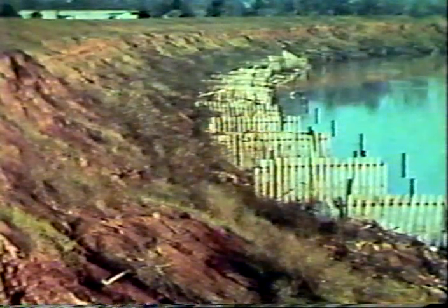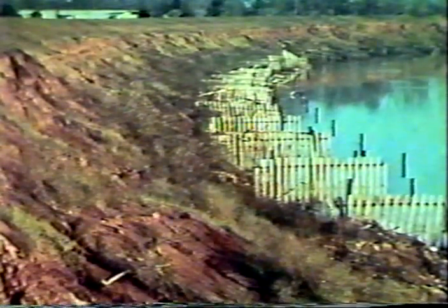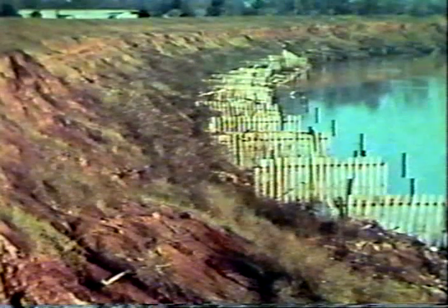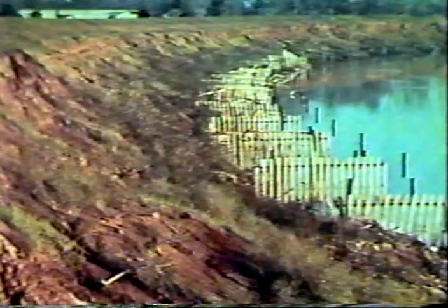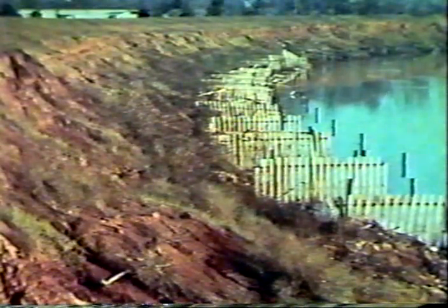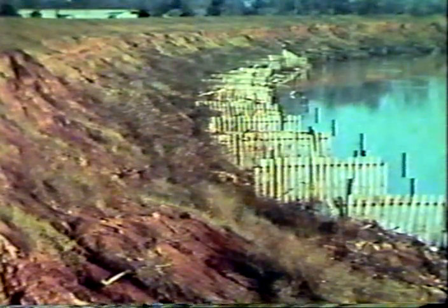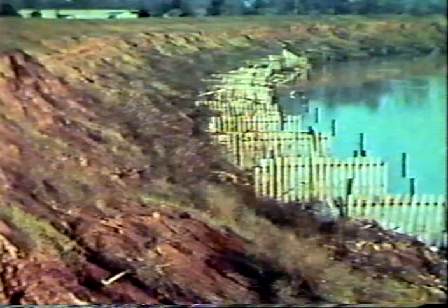These timber pile spurs on the Big Black River in Mississippi, installed in 1950, have successfully controlled the problem of lateral erosion at the outside of a bend. Patented permeable spur jetties, like these on the Brazos River in Texas, have performed well at some pipeline crossings. Permeable panels of timber and steel are loosely bolted to vertical steel pipe pile. The panels slide downward to maintain contact with the stream bed, an important requirement for a permeable spur.